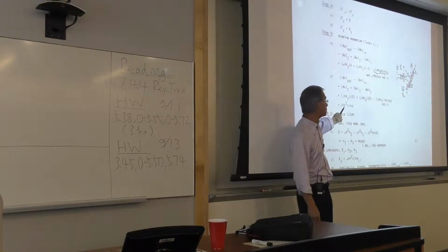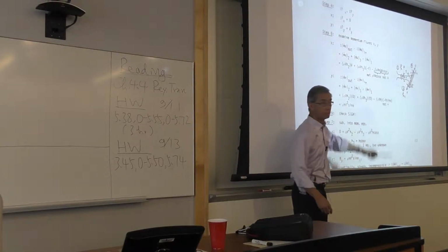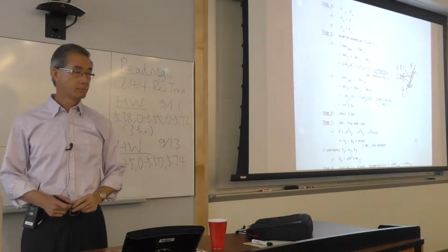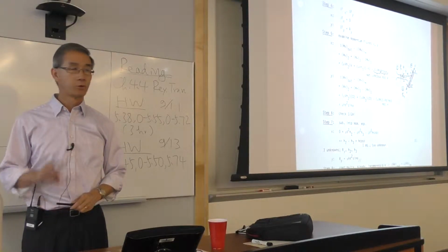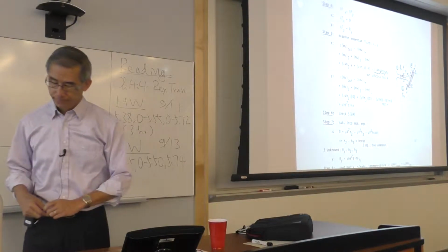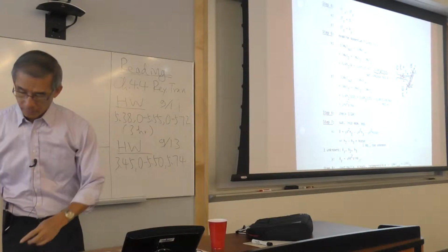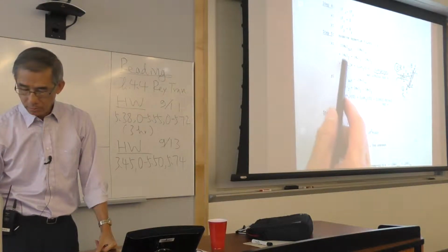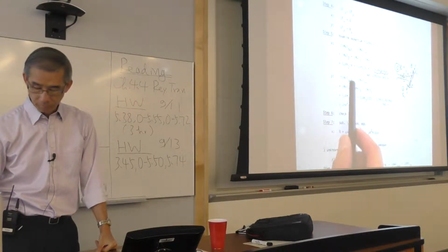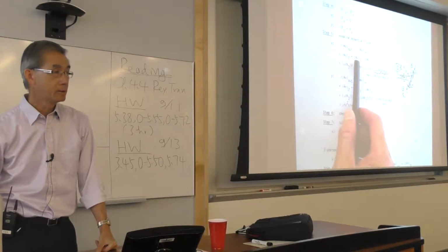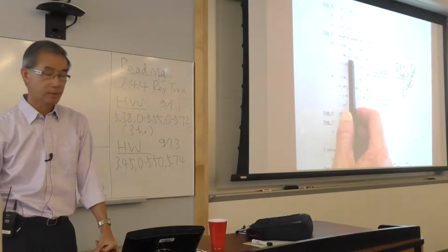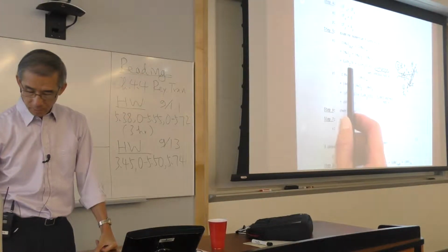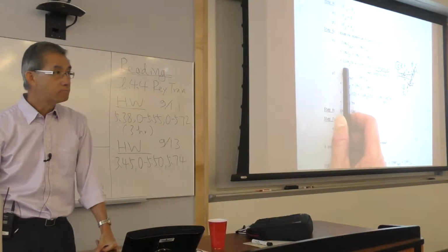All right? So, x momentum, m dot u out, how many stations? How many stations? 2. 2 and 3. In is 1. Only here. So I'm going to break it up into m dot u2, parenthesis, positive, m dot u3, positive, because it's out, momentum flux. Minus is the in momentum flux with m dot u. And here is where the rubber hits the road.